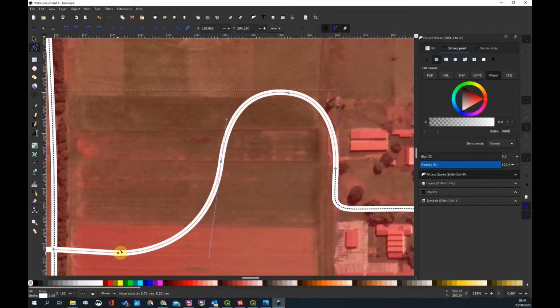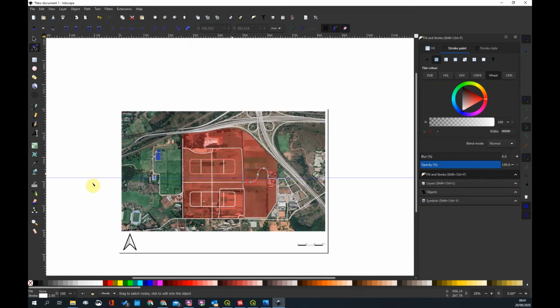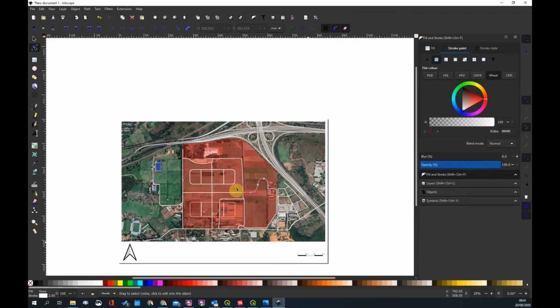So here, for example, I would come out straight, use Control, and it'll lock it straight. So here I want to lock this straight. And you can use guidelines to do this as well. You can pull guidelines in from the side, and it'll make guidelines that you can use as construction lines. If you don't want them, just pull them away. That's it. So you can use those as construction lines.